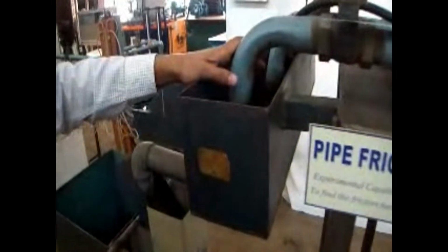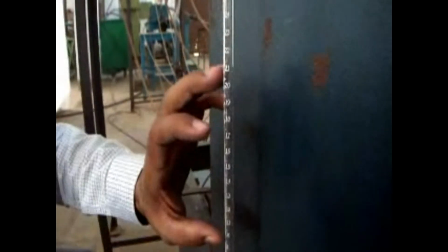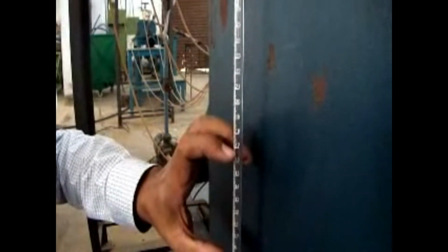And discharge we are measuring by collecting this water through this tank, which has a particular dimension. You can see here, size is 40 centimeter by 40 centimeter, exactly 40 centimeter, and we can measure what is the flow volume per unit time. So if we observe the discharge from any of the pipe for a certain height of discharge or flow that is collected in this tank, so per unit discharge we can find out.